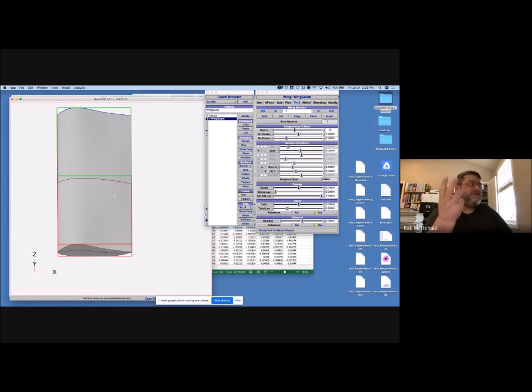So you could say, okay, well, the CG is always in the same place. We know that. We don't need a big CG range. Whereas you can imagine a big military transport airplane where they're going to load Humvees in the back, right? And the next time they're going to load a tank, or maybe they're just going to have a bunch of dudes, or who knows? Maybe they need to deliver 10,000 ping pong balls. You never know where the CG is going to be on a day-to-day basis. And so that transport airplane, you need it to be able to handle a wide range of CGs.